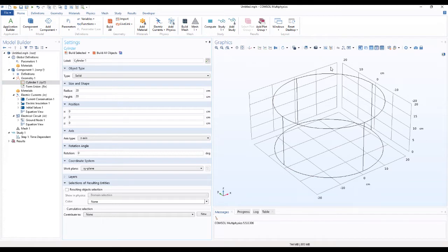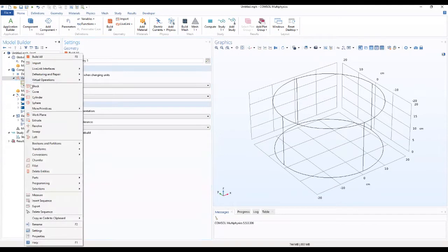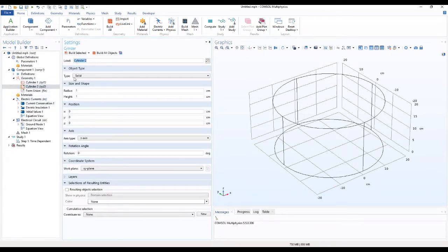So building the geometry is quite easy. Putting in the parameters is also easy. We go ahead to add another cylinder, and same, we input our radius to 10.4. And with this, we want to change the position of the Z to 8.